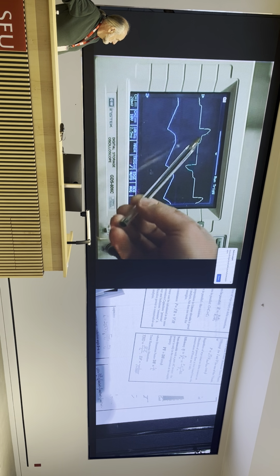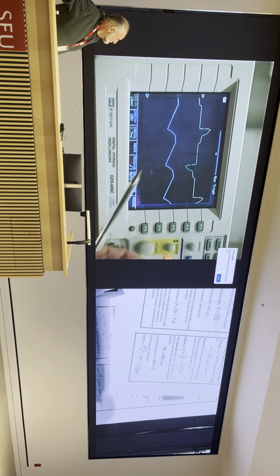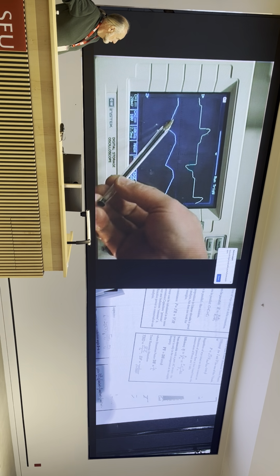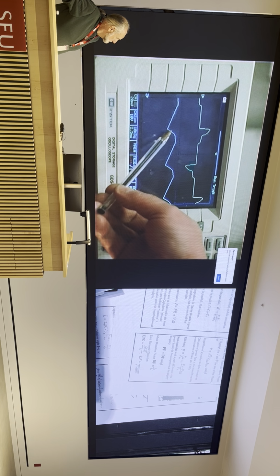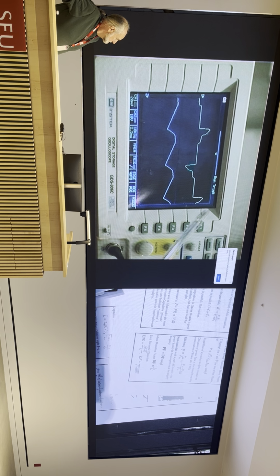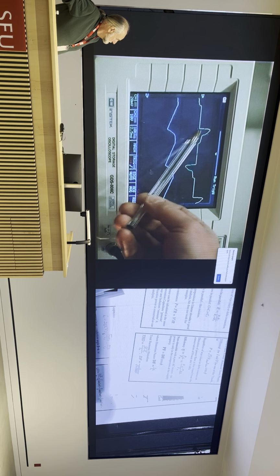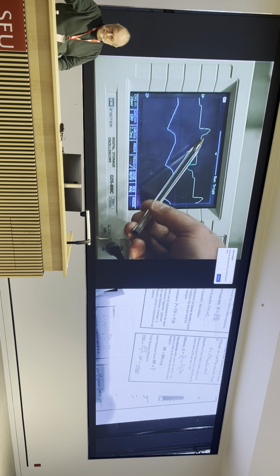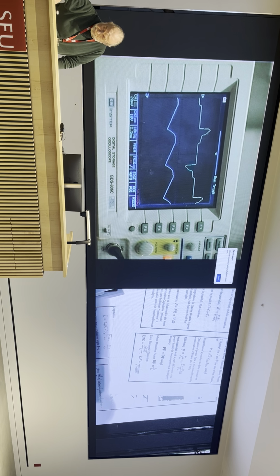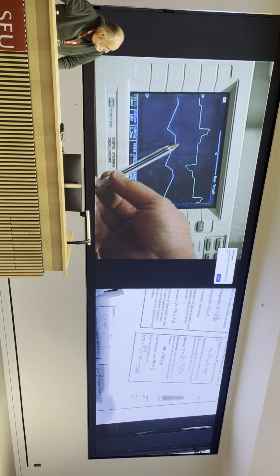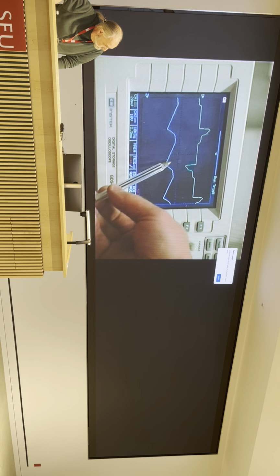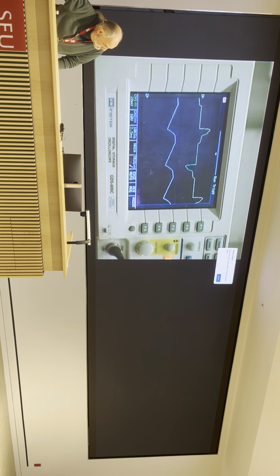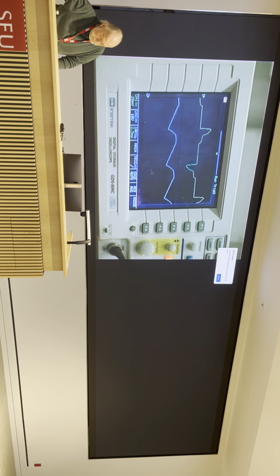You'll see some interesting features here. It jumps up almost instantaneously when the voltage on the capacitor hits the mains voltage, the rectifier comes on, and the current jumps up rapidly, and then drops off as the capacitor is charged up. And it's supplying a low current a little bit there too. During this second period, the low current is supplied entirely by the capacitor, that big capacitor there.